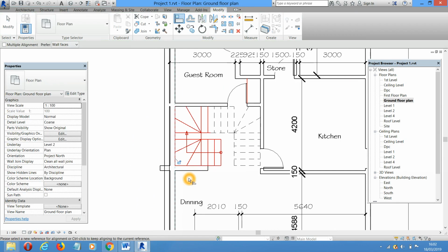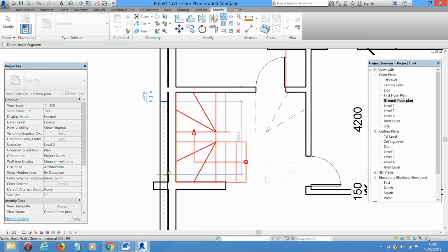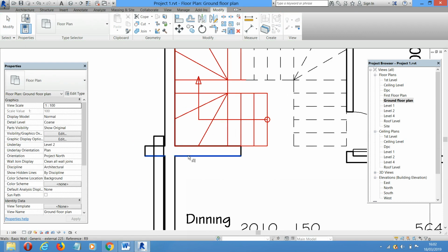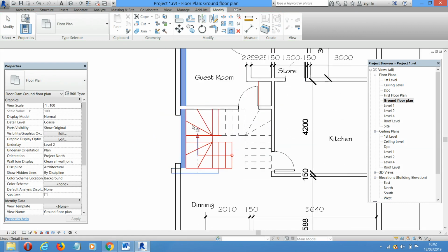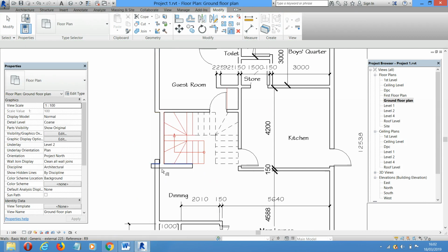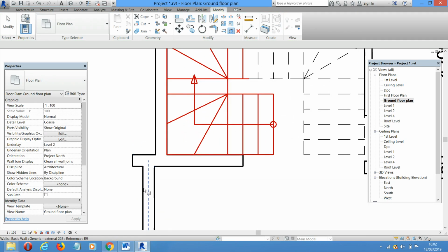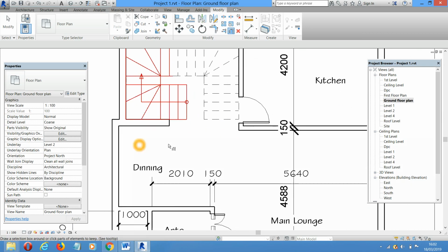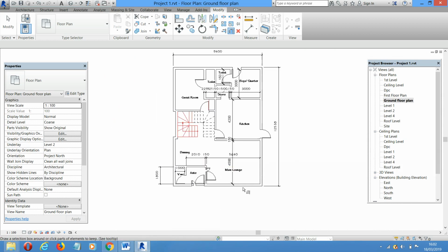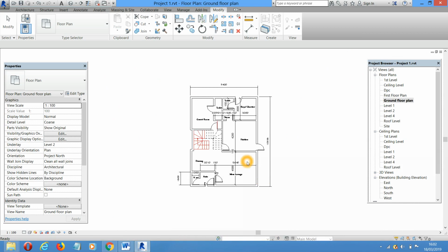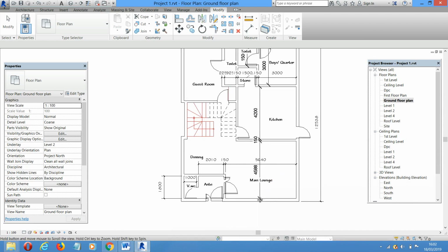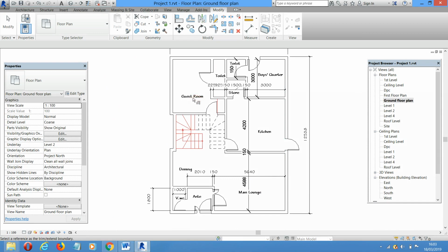I want to have a recess in that staircase area. So I'll use split, SL for shortcuts. I'm going to remove this. Then I'm going to use EX for extend multiple. Alright, this is where this one is going to stop, so that we'll see the staircase from dining. I save my work. Now the next thing we'll be doing is to fix the windows and other designs.